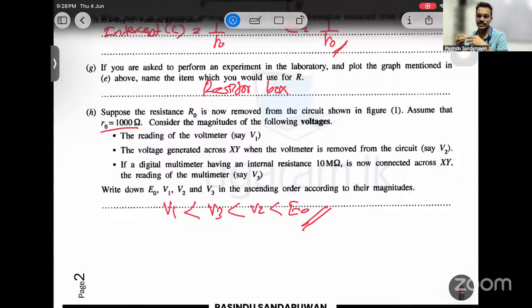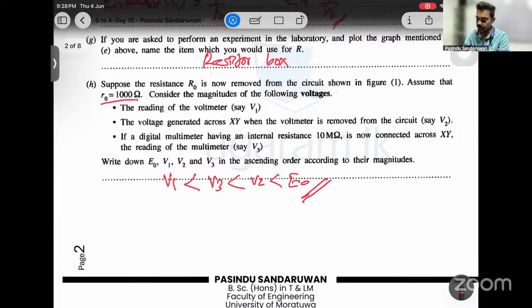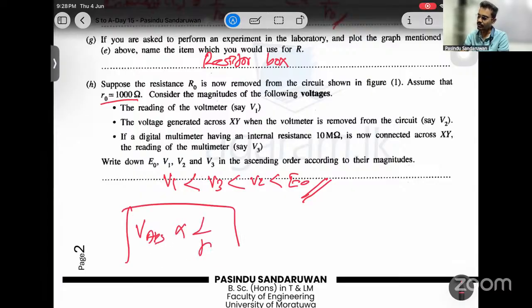That's why in an ideal scenario it's supposed to be infinity. When there is infinite resistance, no current flows at all, which means no voltage absorption. So voltage absorption by the voltmeter and resistance of the voltmeter are inverse. Higher the resistance of the voltmeter, lesser absorption. Lesser absorption by the voltmeter means a more accurate reading is given.